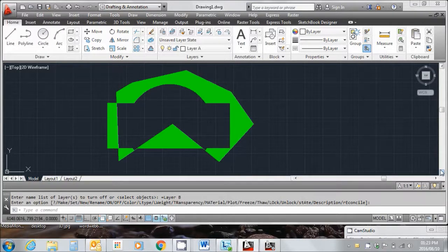So if I want to do a water network design, then I'll put all my water pipes in one layer. I'll import my drawing into Civil Designer, and then I'll say, where are the water pipes? The water pipes are in the water pipe layer. And then it will extract the water pipes from that layer. Now the beauty of that is you can keep everything neat and tidy. If you want to create multiple layouts, showing one services or two services, you can switch some on and switch some off. And that's really the gist of how we're going to be operating.